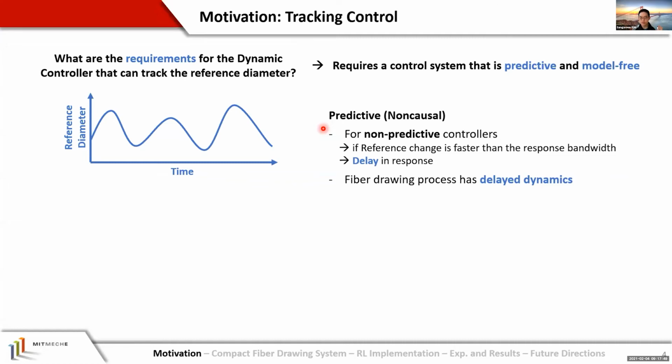And if we look at the fiber drawing process, the process involves significant delay dynamics. So for example, if we change the feed rate of the preform, then the response in diameter will show up several seconds later. Therefore, if we just use the PID control, the tracking performance will be very poor.